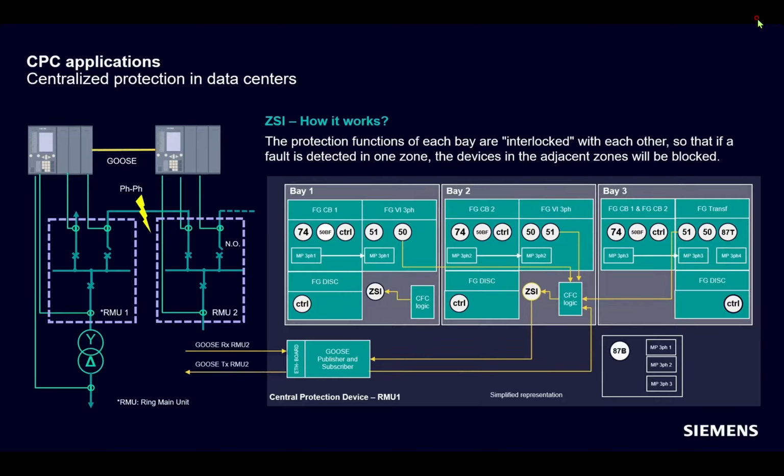The signal trips bay 1 in centralized protection 2 because it's published via GOOSE. Then the circuit breaker assigned to bay 1 is also opened. Now the fault is cleared, and one automated transfer can close the circuit breaker that is normally open. With this scheme, we have selectivity, and none of the loads are affected.